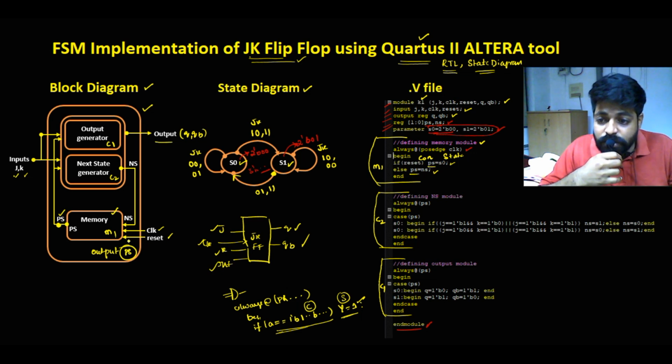What is this about? So he is saying that when the reset is given, the particular memory needs to start with the count 000 if it is a counter circuit. In a similar fashion, if it is a memory, irrespective of the state it is in, it should come to the zero state. That is called your S0. So that's what I'm trying to mention. If there is a reset, the present state should come to S0. Otherwise, it goes to the next state.